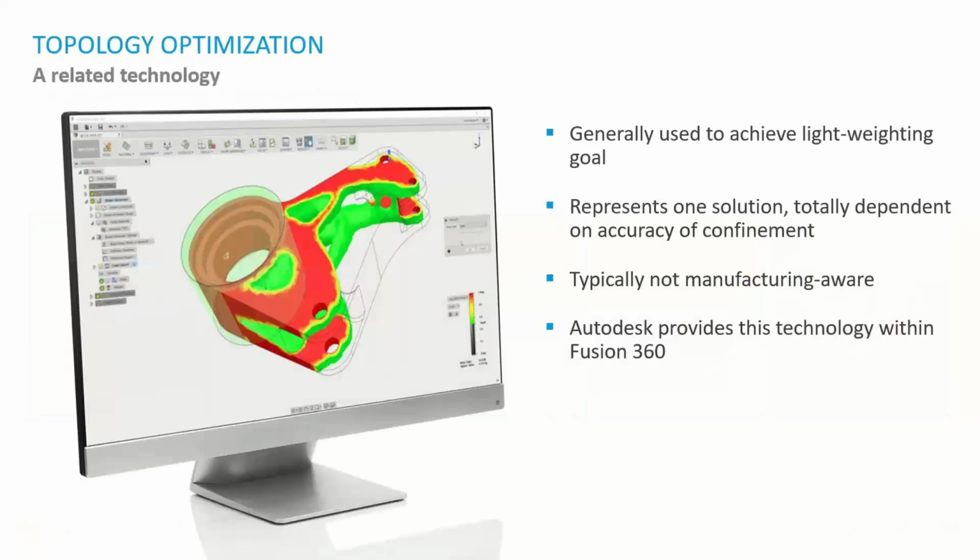You might say, Steve, okay, well, we've had Shape Generator in Inventor for 4 or 5 years now. How is this any different or any better? So with the Shape Generator, that is really topology optimization. It is similar in the fact of how we're going to set things up. But the difference here is when we get that out, it is just basically a mesh file. We have one option. It's not manufacturing aware. It doesn't know how I want to manufacture it.